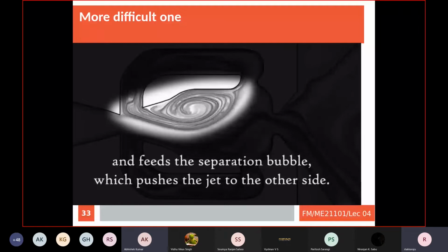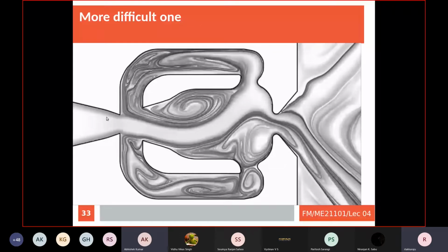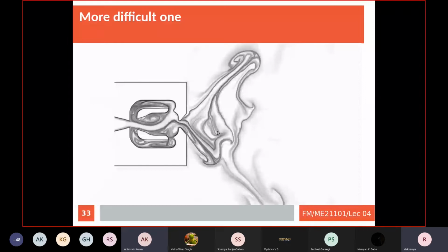Once you achieve that, immediately you switch off that fluid which is entering that nozzle. That is the way you suddenly, quickly get something named thrust. Because your mechanical things, you cannot really change them quickly. For example, maybe I can have some mechanical device, maybe a servo motor which I will divert so that my nozzle goes in the downward direction, so I can get a thrust.